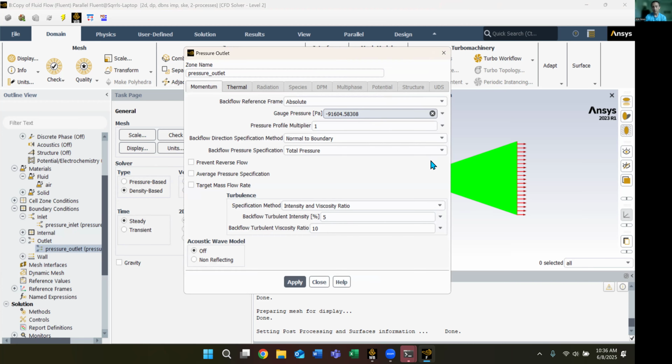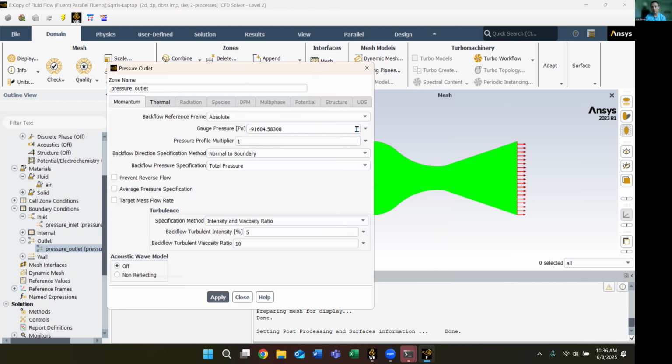After doing the calculations, I calculated the back pressure for having the shock in the throat of the nozzle and the shock at the exit of the nozzle. Then I just chose a value somewhere in between, trying to get it close to about halfway.